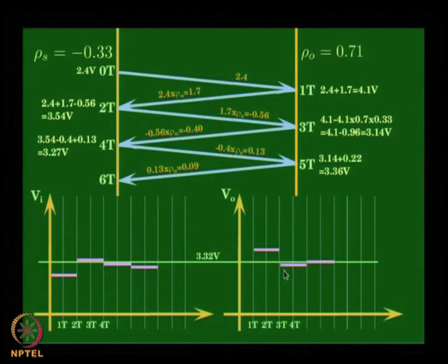Let us say if this had gone sufficiently down, then you could see that the output stage circuitry would go low rather than go high, and then once again when it comes back it will go high. So, you will have double pulsing and malfunctioning of the circuit. So, this is one of the serious problems that we see with reflections.